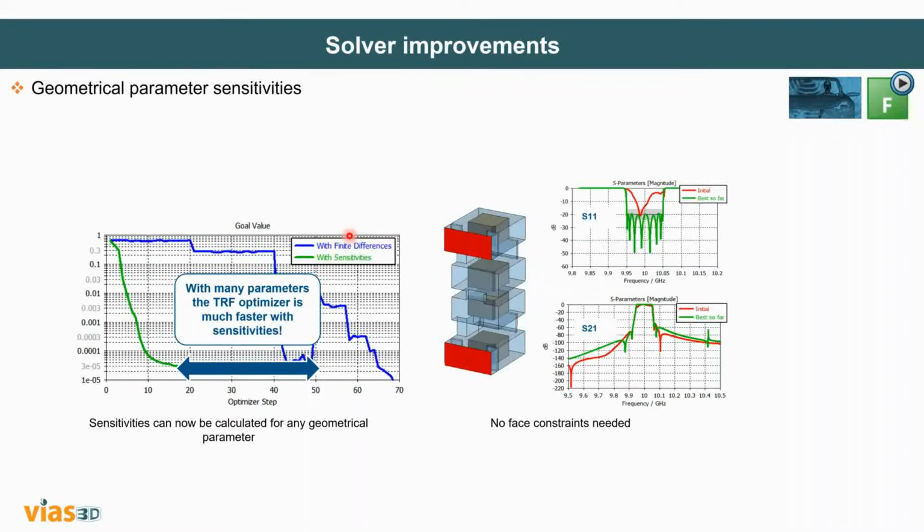So further, we can see the solver improvements on the geometrical side. For many years we have had a tuning slider in the circuit environment, but now finally we also have this for 3D models. When the sensitivity analysis is executed along with one of our high frequency solvers, in post processing you are able to instantaneously tune the S parameter option. Now simply right click on the S parameter folder in the tree and activate the sensitivity tuning.